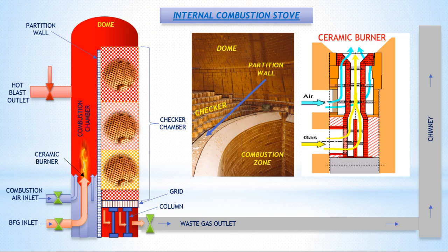The dome is typically made from high-temperature refractory materials, like castable refractory, ceramic fiber, etc. The dome's curved or arched shape promotes even heat distribution and helps contain the combustion process. The dome may be insulated to minimize heat loss and optimize heat transfer.